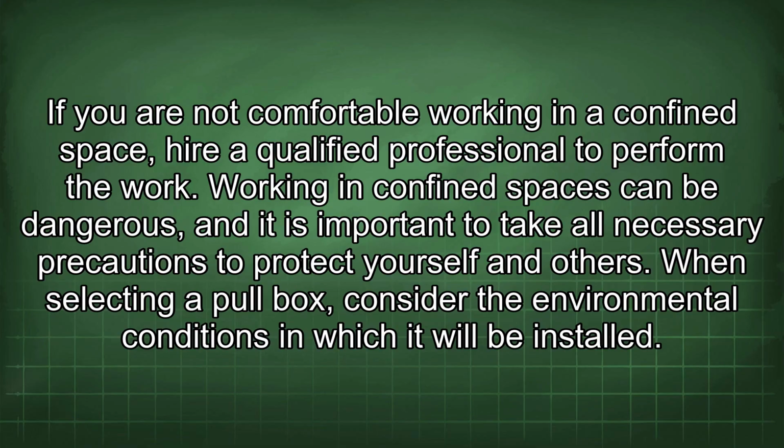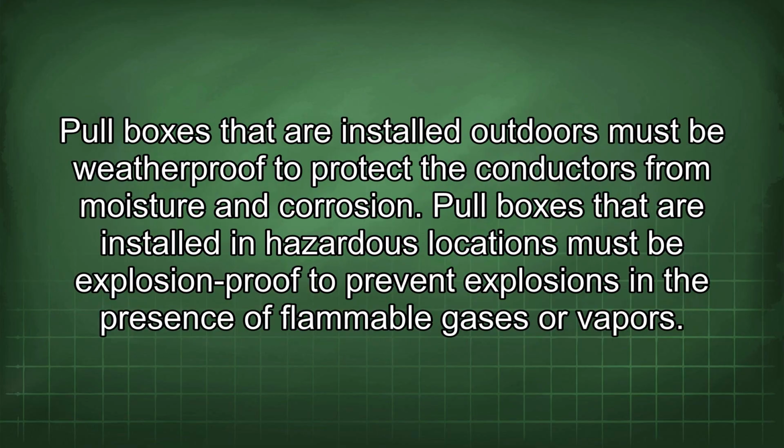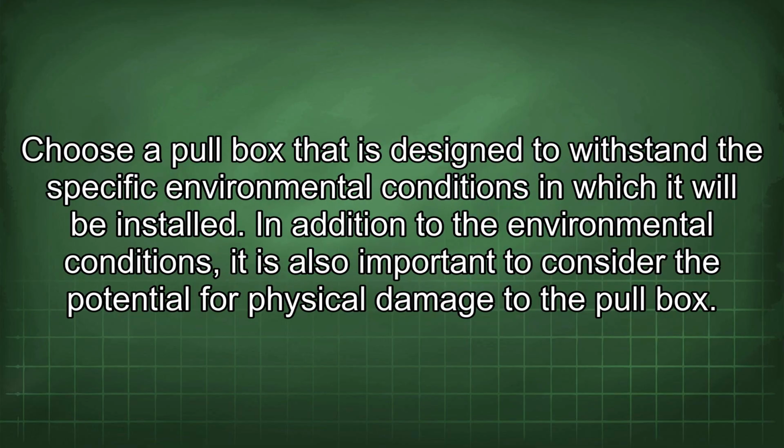When selecting a pull box, consider the environmental conditions in which it will be installed. Pull boxes that are installed outdoors must be weatherproof to protect the conductors from moisture and corrosion. Pull boxes that are installed in hazardous locations must be explosion-proof to prevent explosions in the presence of flammable gases or vapors. Choose a pull box that is designed to withstand the specific environmental conditions in which it will be installed.